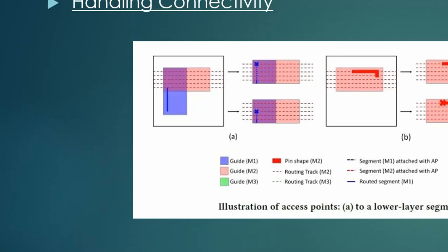So that's where the second picture comes into play. You have a routing in metal layer till this point, and now you have 5 points where you can connect the vias. So it could be at the intersection of this line. In this picture it has just shown the 2 points at which the via can be placed. So either you can place it in the upper or you can place it here in second.